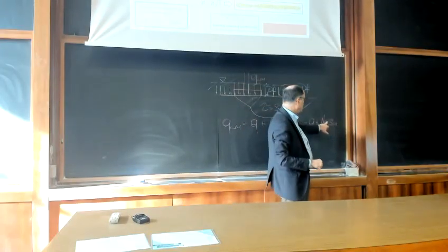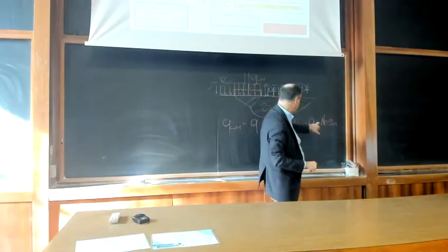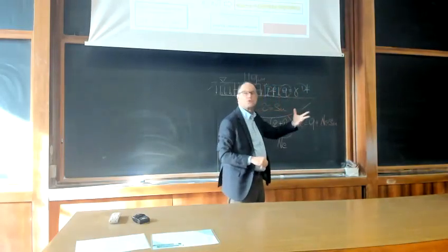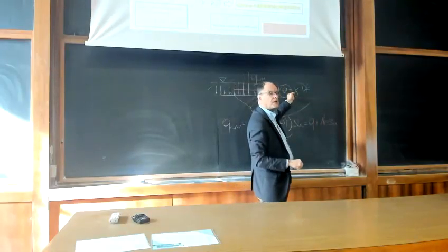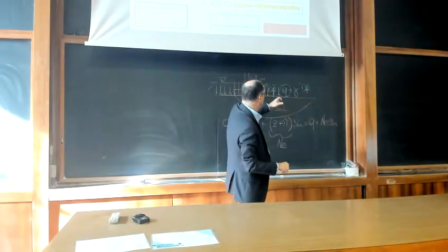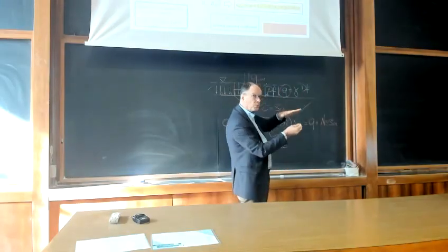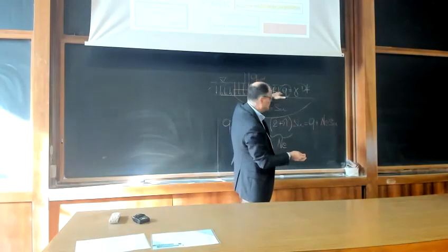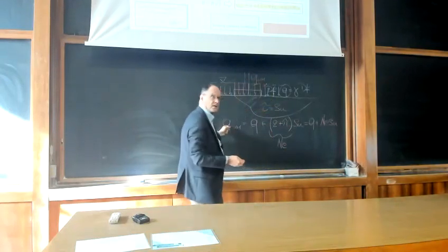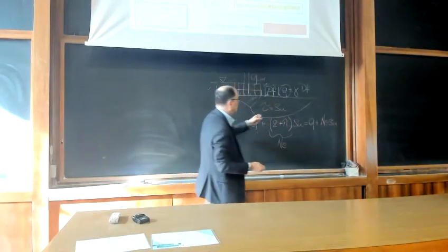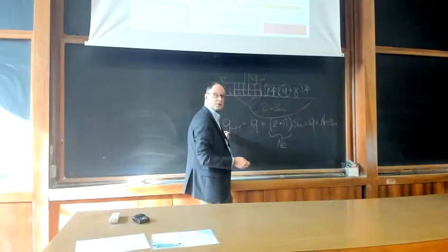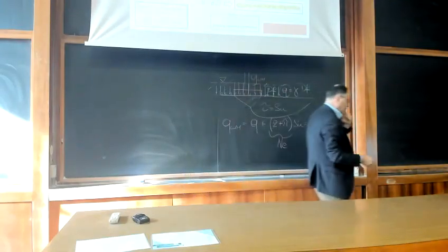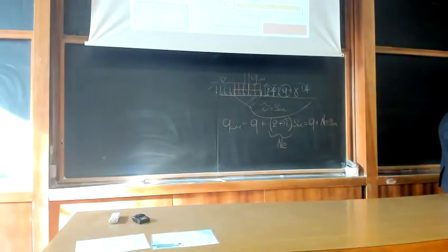But we notice that this is a function, of course, of the undrained shear strength of the soil, of this bearing capacity factor, which is 2 plus pi, so 5.14, something like that, and the contribution of the overburden stress, which tells us that the deeper the foundation, the higher your limit load, because if you increase this dF, you increase this, and you increase your limit load. So this is the first result we can get.